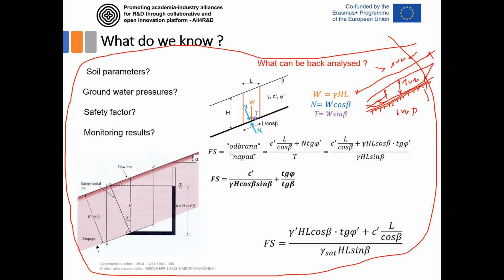It's not possible for water to go down. It's going down the hill and then going to some river down there. And very often we have slidings like this due to water increment, especially if we do some excavation at the bottom here, or we put some additional load up on the hill, and so on.